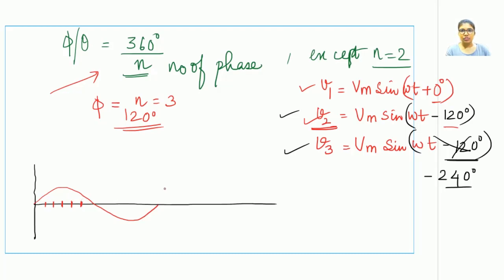Why did I do it like this? It is because I have to draw the second waveform, and the second waveform has to start from 120 degrees of the first signal. So where do we get the 120 degrees of the first signal? As I had said, divide this sinusoidal half waveform into 5 points. The midpoint represents 90 degrees and each point is at 30 degrees.